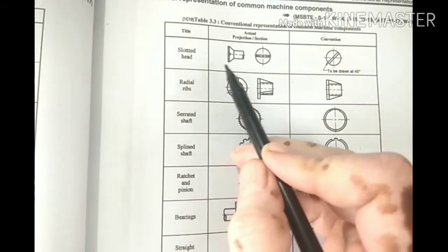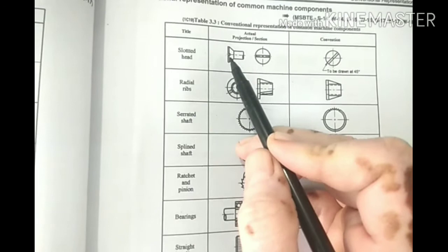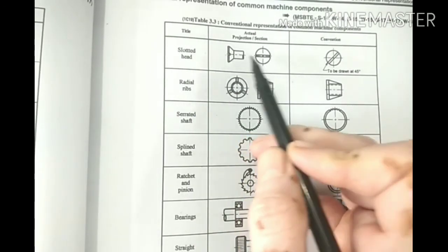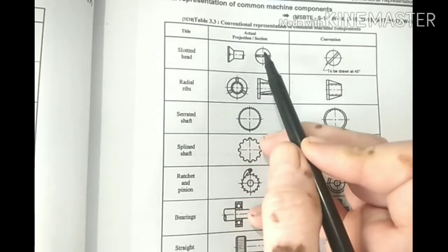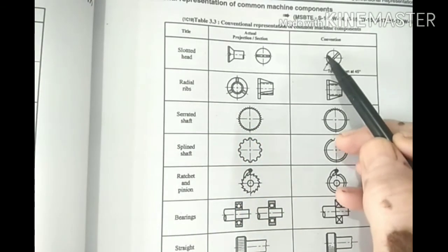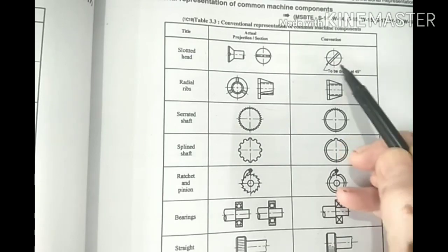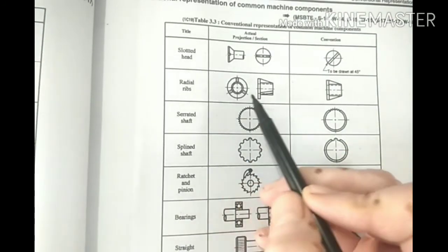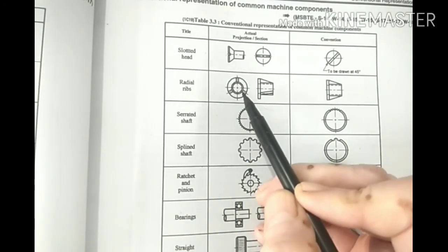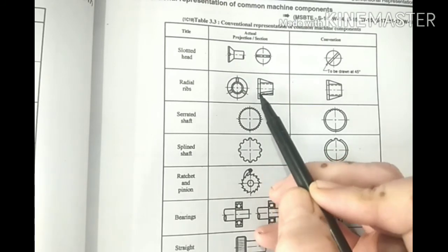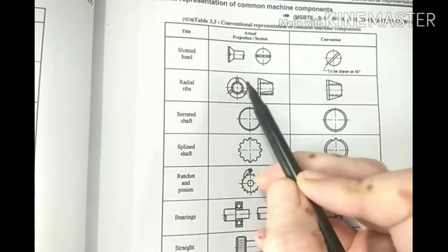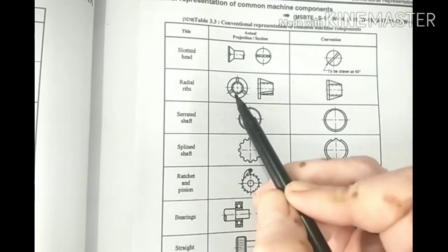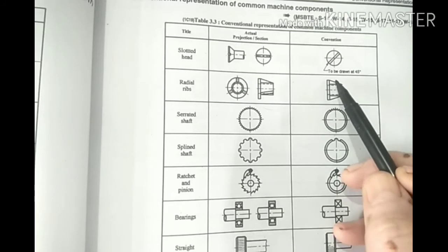Slotted head. If you are using screws or bolts with a slotted head, the actual drawing is like this front view or side view, and conventionally it is represented by a circle and two lines of slot at an angle of 45 degrees. If there are radial ribs, it means there is a cylindrical part, and these two cylindrical parts are joined by the rib, so the front view and side view will be like this,